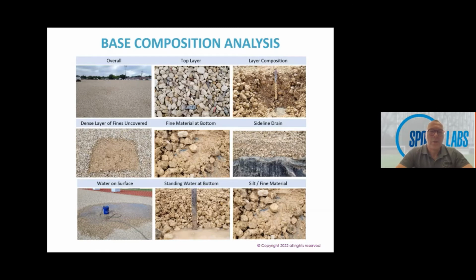And then you've got another scenario there where the top layer is quite uniform, and then as you excavate down through the layer you get into fine materials, and eventually when you get to the bottom of the subbase layer, it's holding water on the subgrade, which will fill up eventually, and you could have another problem with drainage. So these are kind of things that we see when we're asked to come in and inspect or test subbase materials, and Mark, as I say, Mark will highlight some of these a little bit in a few minutes. Next slide, please.